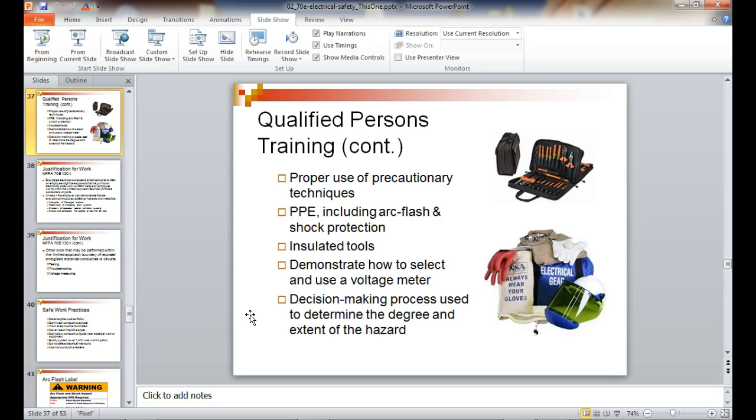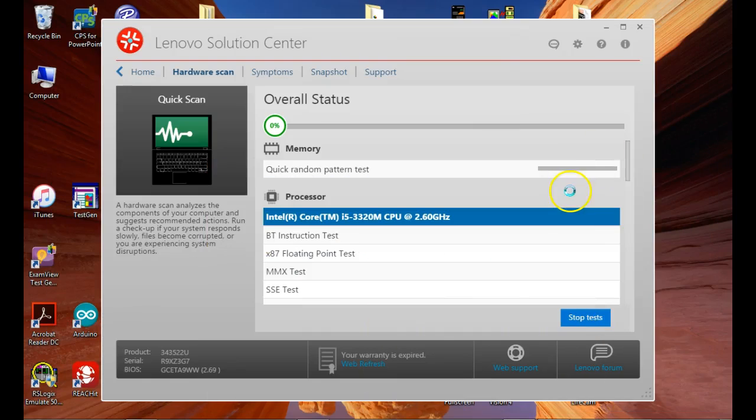Used to, when you got a meter, you just looked at the highest range the meter would measure, and you would say, okay, the highest range is 2,000 volts. That means I can measure 2,000 volts. But what they understood later on is that the electrical power that we have is not steady.